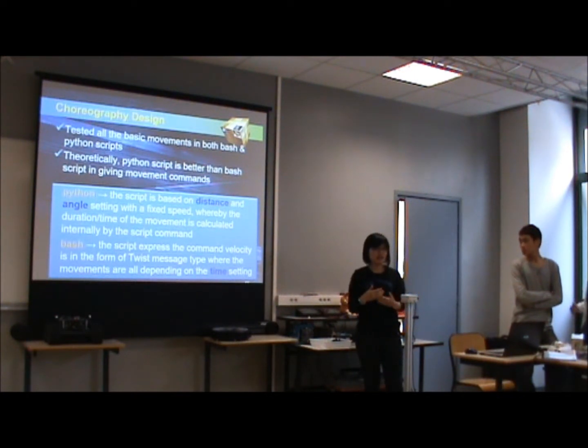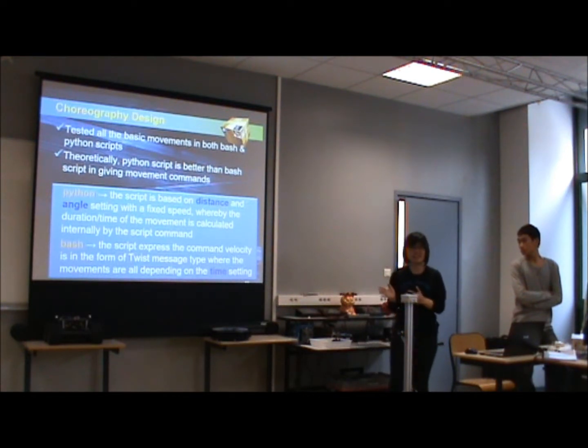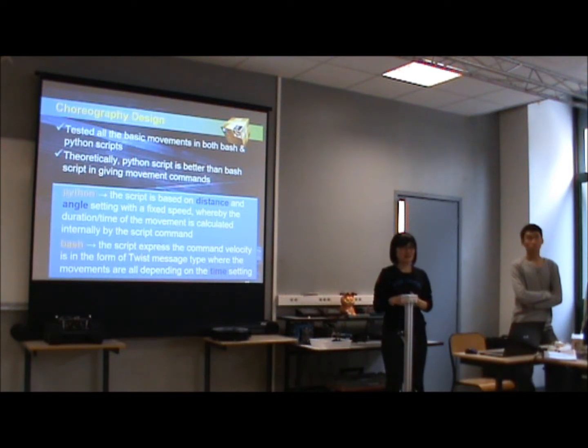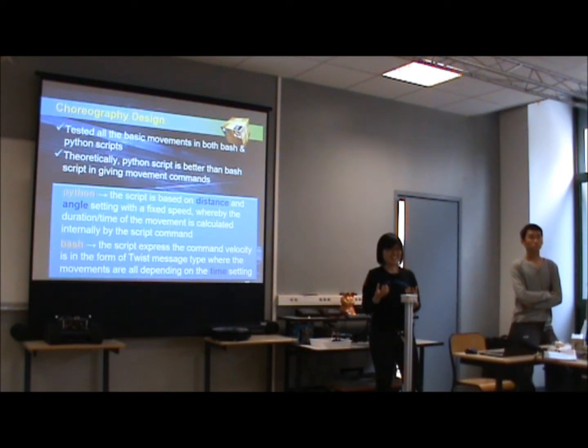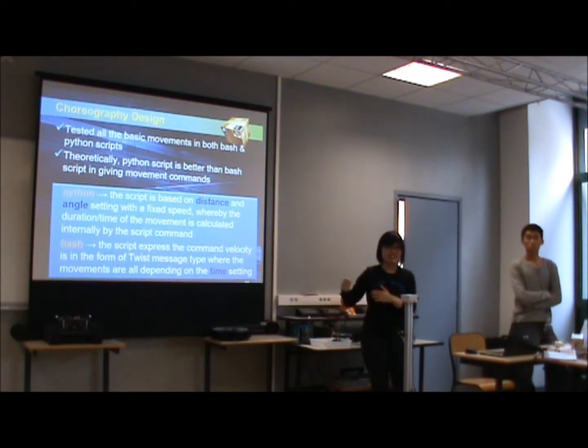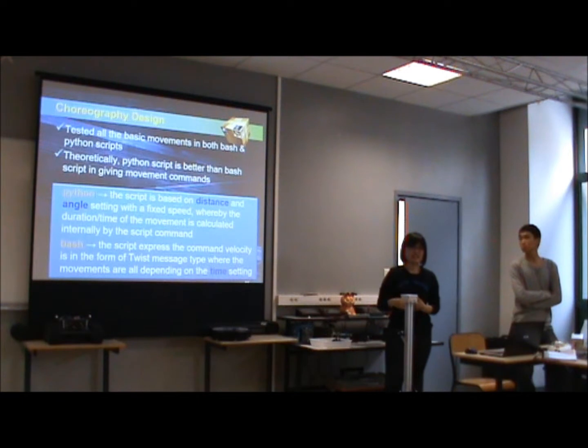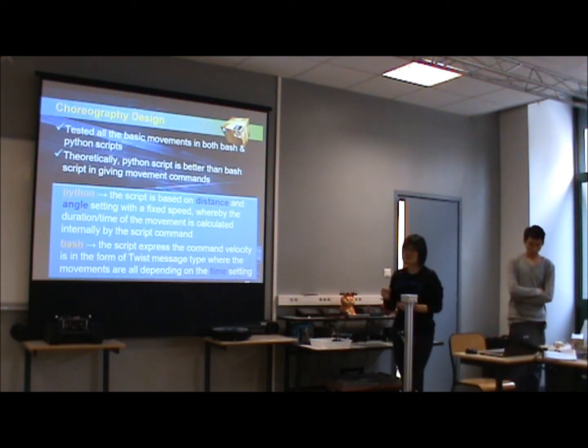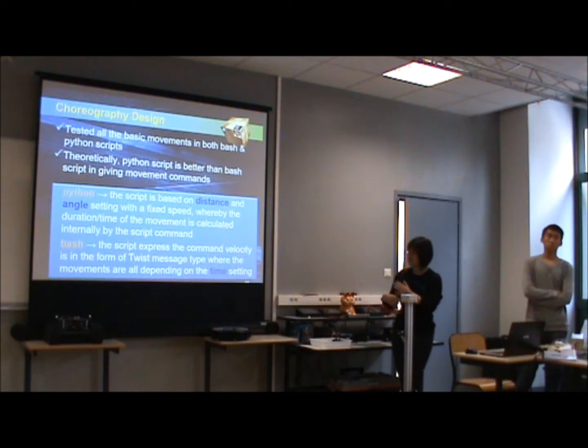However, I tried a few times using Python, and even though it's supposed to turn, let's say, 180 degrees, maybe due to some other factors, the smoothness of the rotation of each TurtleBot is different. I tested yesterday, and I gave the same command, but one moved 180 degrees and another maybe 170 degrees. The slight difference of 5 degrees will eventually cause the direction of the next move of the TurtleBot to deviate from its route. So that's the problem I'll be looking into in the future: how to solve the slight deviation of the rotation.